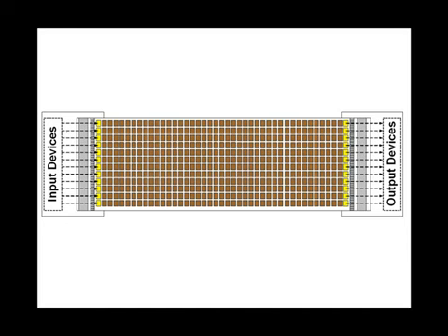The column of yellow relays on the left end of the control panel are unique in that their coil voltages match whatever the field voltage is used for the various input devices. So some input devices are 5 volts, some are 24 volts DC, some are 115 volts AC. So you have to have a relay coil.